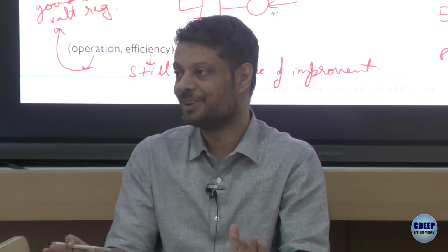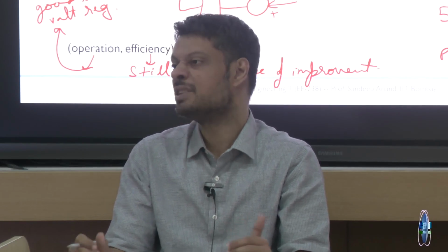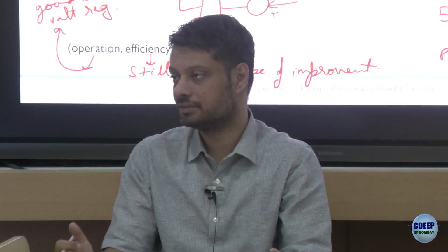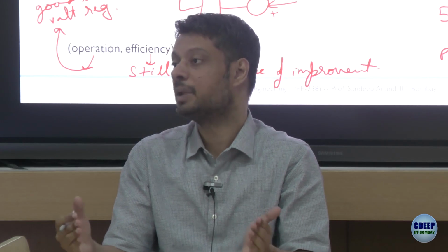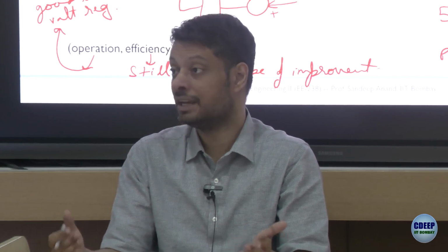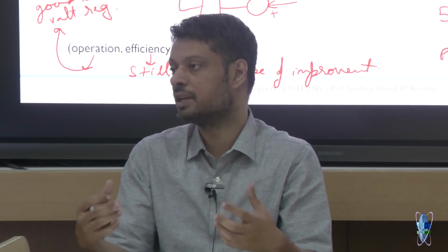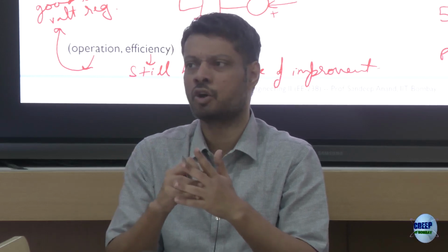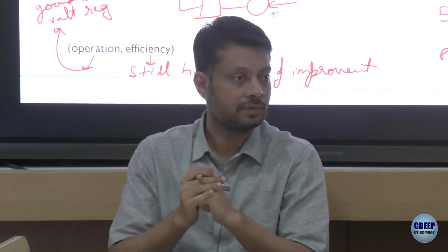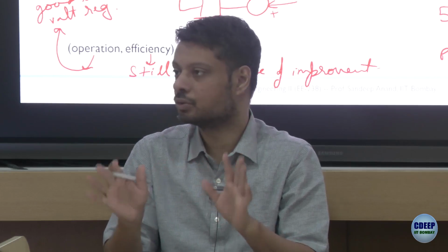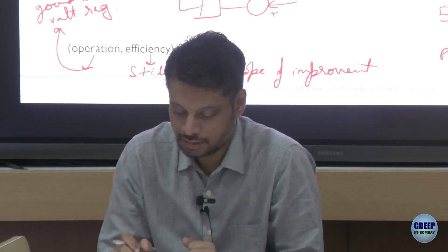So by no load, we mean there is no current, which implies that the resistance is infinite. By light load, we mean small current, implying resistance is very large. By heavy load, we imply large current, meaning the resistance is small. So load means basically we are talking about load power or load current, not the resistance. This is the terminology very commonly used, at least for this course and for all the power related courses.